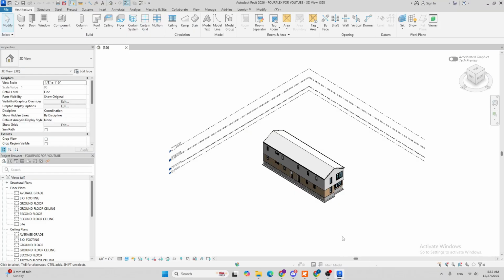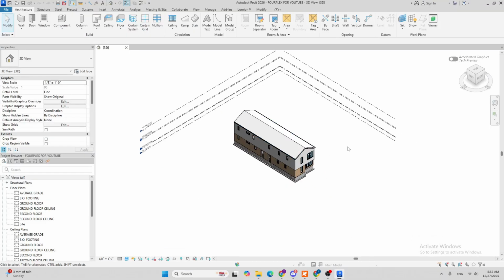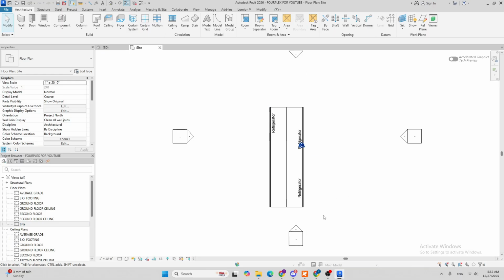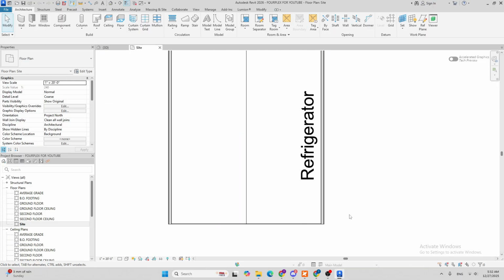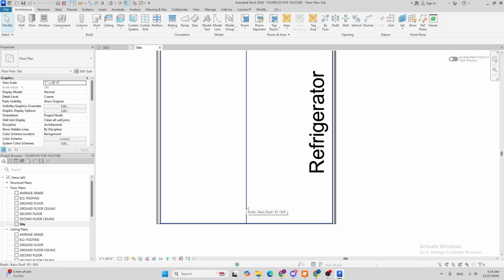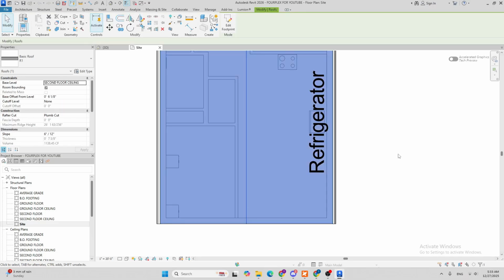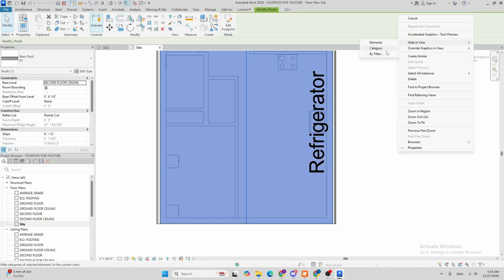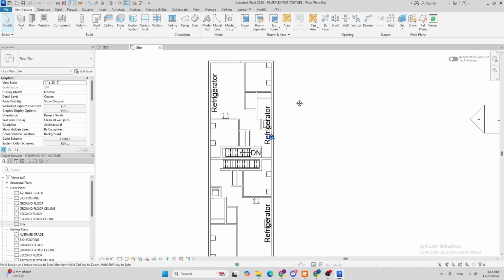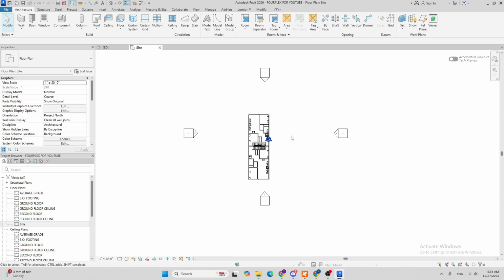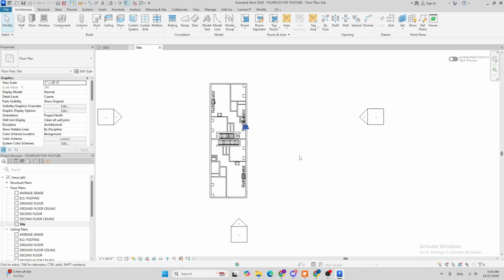From our Revit, you're gonna double click on your site plan right here, and I'm gonna hide the roof and the gutters and everything related to that group on the site plan. So I'm gonna click the roof, right click, hide in view, category, so it hides everything related to that category. So at first, let's draw the property line.